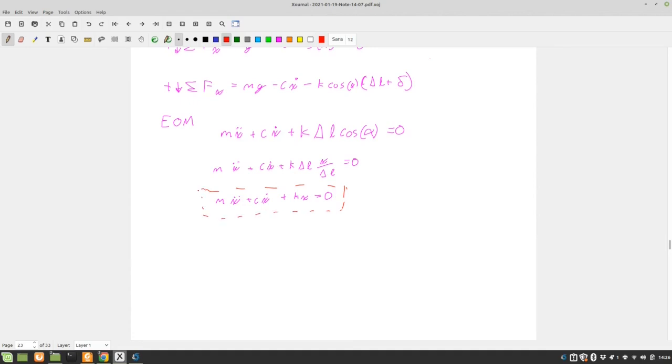Right? So now if you want to know your damped natural frequency, it's omega d is equal to omega n times the square root of 1 minus zeta squared. So that seems kind of hand wavy, right? But just showing you that it's not an obscene assumption to assume that those are the same. So we get back to our same natural frequency.